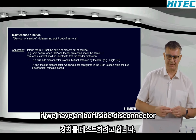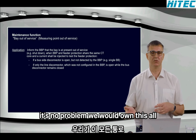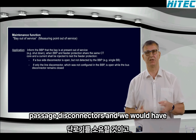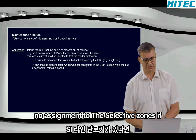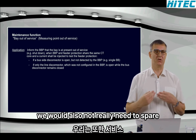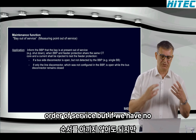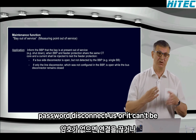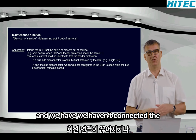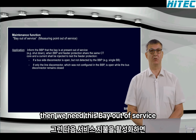If we have a bus side disconnector, it's no problem. We would open all bus side disconnectors and we would have no assignment to the selective zones. If we have assigned line disconnectors, we would also not really need this bay out of service. But if we have no bus side disconnectors or they can't be opened on the primary side, and we haven't connected the line disconnector to our busbar protection, then we need this bay out of service.